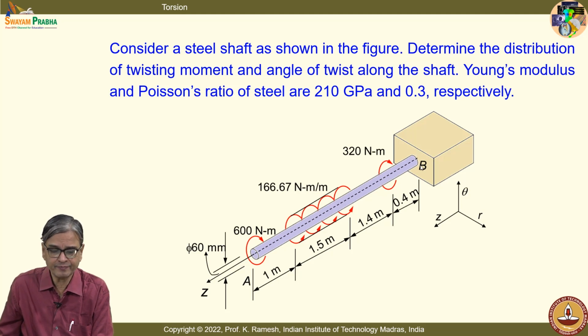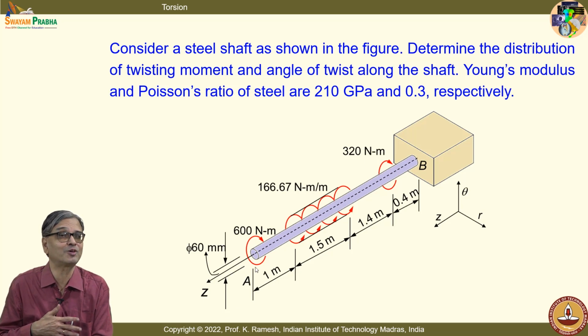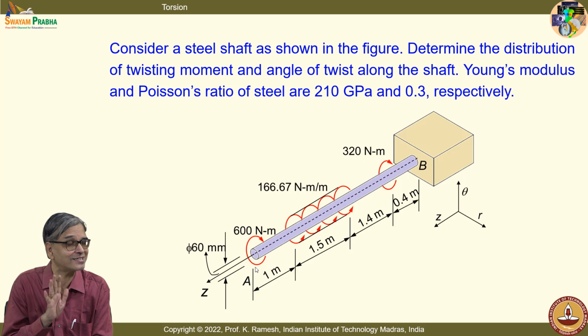So, you have NB fixed and NA free, fine. Your angle of twist will be maximum where? Along the length of the shaft. It is a free end, but when we graduate and then come for interview, when you ask this question, students always get confused because they see there is a maximum twisting moment here, they also think that that is where the maximum angle of twist is there. This confusion is there. So, I am warning you, so learn it clearly.